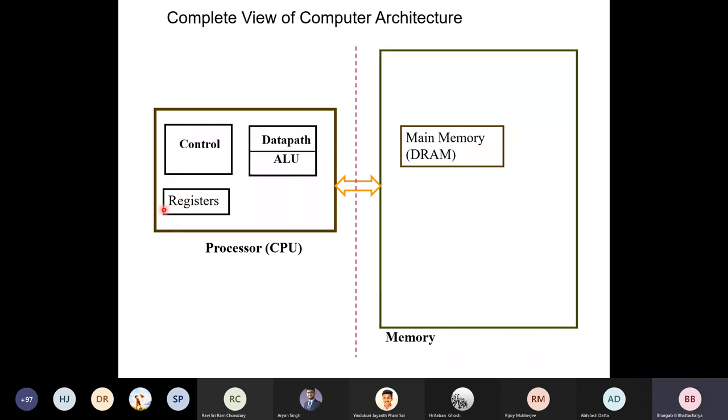The registers can also be thought of as some memory, but registers are essentially flip-flops, that means cross-coupled NAND gates or NOR gates with some additional logic. So that's why register access is much faster, but it is costly. The main memory is a little slower, because the memory technology here is called dynamic RAM. These are not flip-flops.